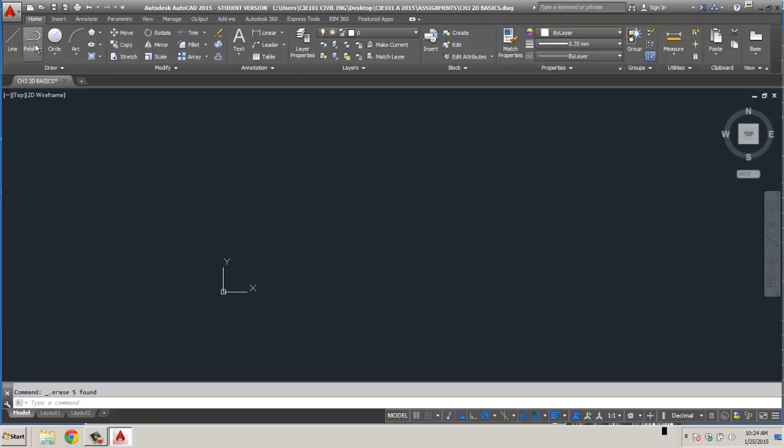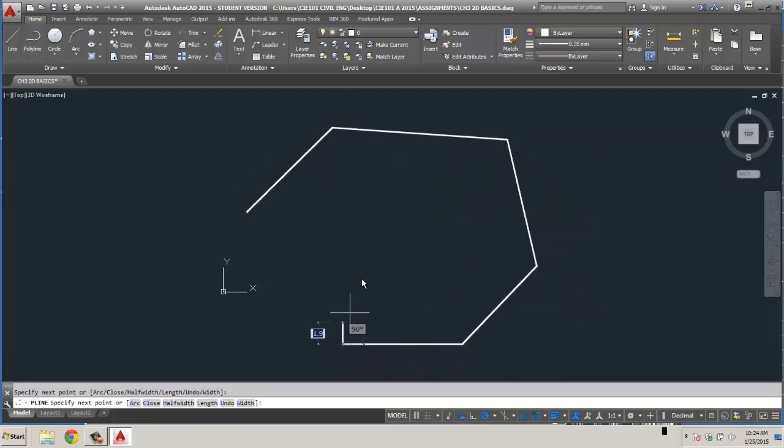If you have a really odd polygon, something using a polyline, and I just hit the C key, enter, it will close the object and make a shape out of that polyline. So it makes this area. So you can do odd shaped polygons.